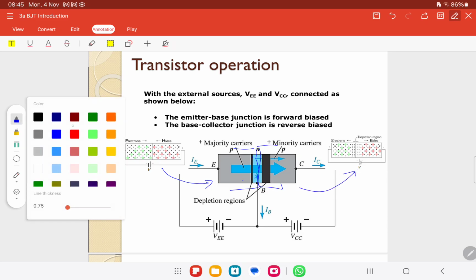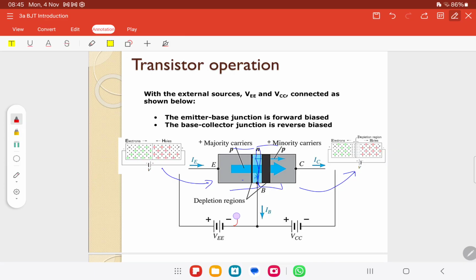And the concept is the same as in the semiconductor. When we put an external electric field, it will disturb the concentration gradient in the PN junction itself. This one is when we do not have the depletion region, forward bias. For this one the depletion region is wider, it is reverse bias. Okay, same concept, same explanation as in chapter 2.